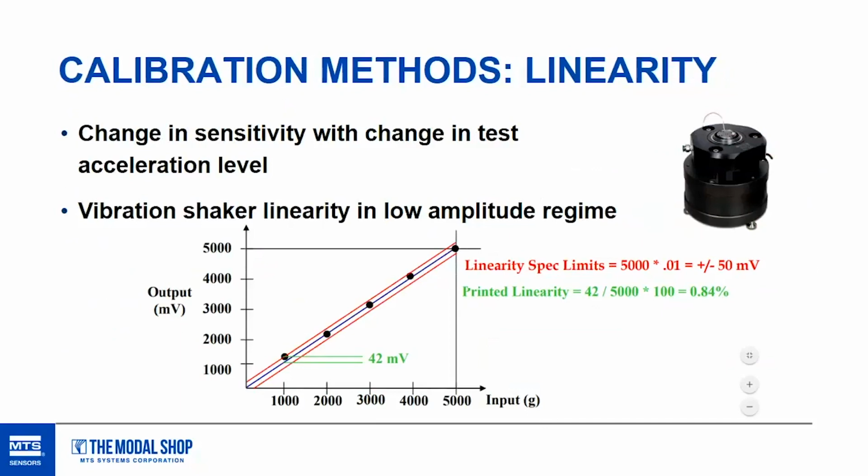You're going to be vibrating a payload on a shaker continuously with increasing levels of test amplitude. And thermally on that shaker, there's going to be some sort of limit that defines how warm you can get based on the force that you're generating with the coil, which is ultimately a factor of how much current you're running through that coil. So there is a limitation if you're doing step sine as to how high you can achieve in an output. But with different methods of excitation of that sensor, we can extend that up to 5,000, 10,000 Gs. The method is typically the same between these though.